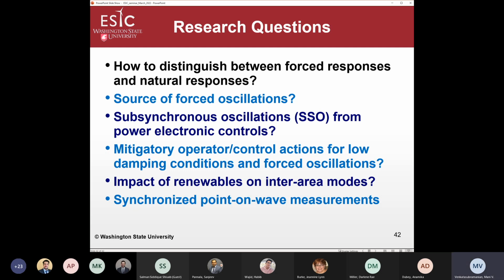So there is a lot of effort going on in understanding what causes these subsynchronous oscillations in wind plants and solar plants, and how to control them and how to keep them at a reasonable level. Inherently, these power electronic devices have high frequency switching internally in how they interface with the grid. So the oscillations cannot be eliminated, but our responsibility is to keep them reasonable so that it doesn't cause a problem for the system operation.